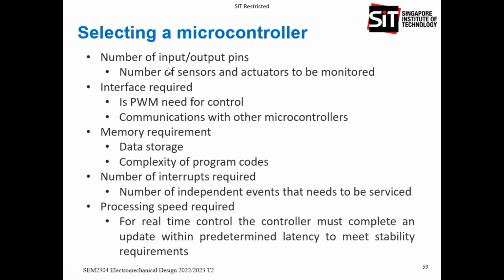Okay, and then the interface. What kind of interface do you need? Do you need analog? Do you need digital? Do you need PWM? Like the picture I showed you earlier, for the main microcontroller to talk to the ESC, they actually use PWM. They don't use a communication protocol. But if you are talking to a GPS, then you need the communication protocol.